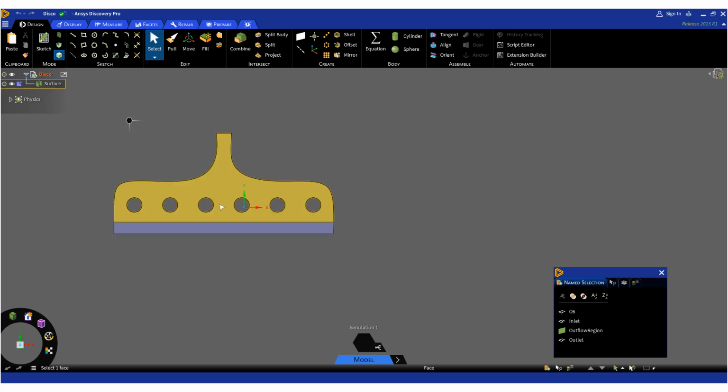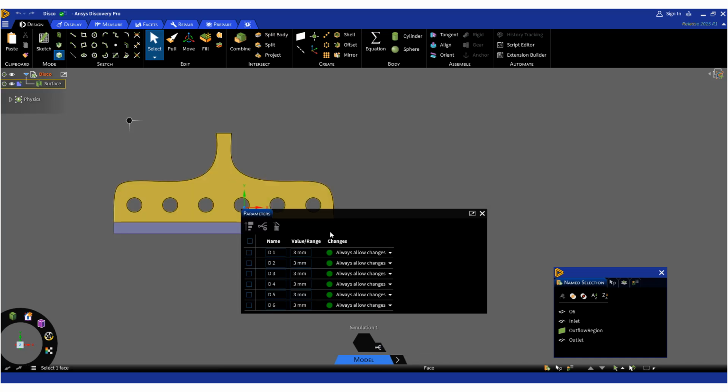So I have 6 openings in this geometry. You can consider this as a very simple, simplified shower head, and we're going to let the water come from the inlet and then leave from the outlet. And we'd like to achieve a certain uniformity and then a pressure gradient. That's going to be the target of this optimization. You can also notice that this geometry is not perfectly symmetric, and that's going to allow us to see the impact of the diameters of these circles, because they are the parameters, and the parameters are pretty much shown here.